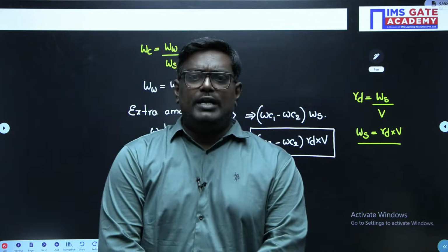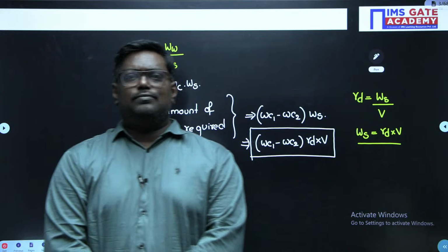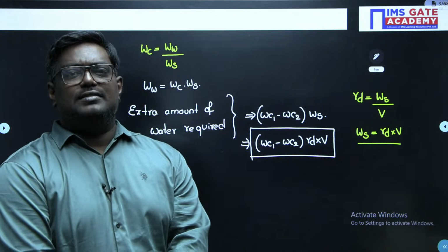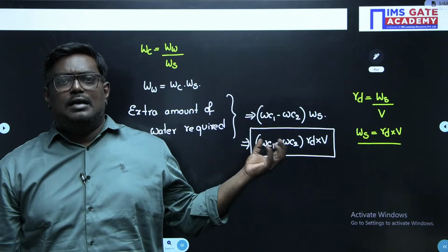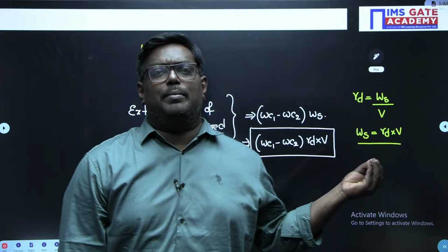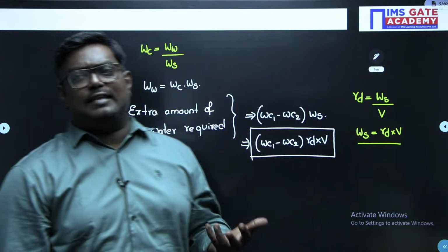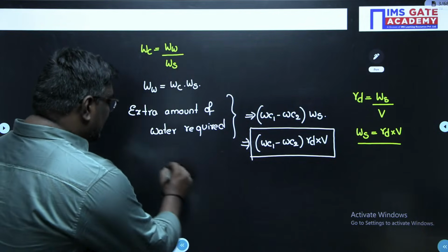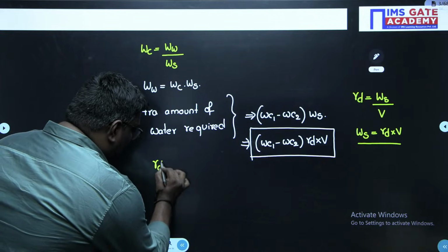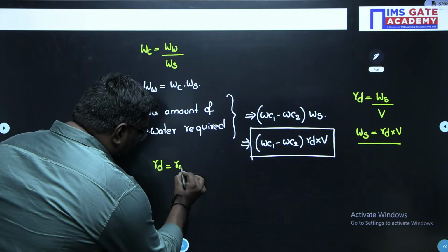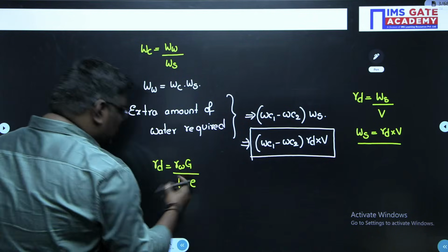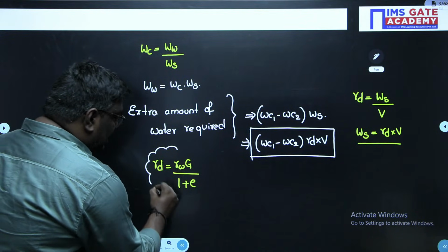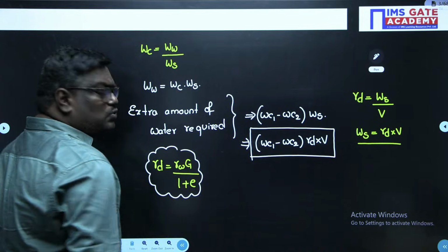Now, my dear students, when I talk about dry density, what is the formula for dry density? So, let me tell you, when I am explaining this problem, it is not only just solving that problem, I will give you some insight where it is required. So, here gamma D is given as the formula. Gamma D is equal to gamma W into G upon 1 plus e. So, this is the formula for what, sir? Dry density, my dear students.